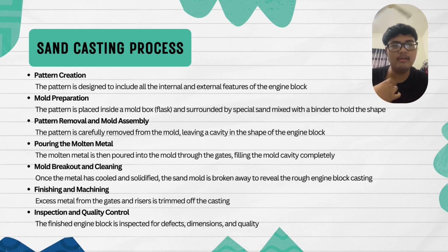Sand casting is an affordable process, particularly for small to medium-sized production runs. Compared to other processes like investment casting or die casting, the initial setup expenses for sand mold and pattern creation are comparatively inexpensive.